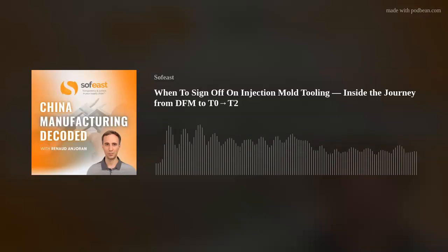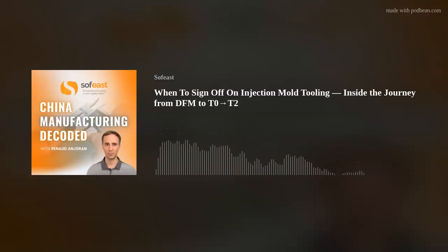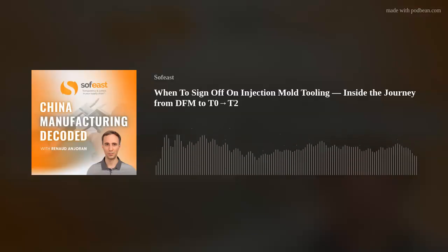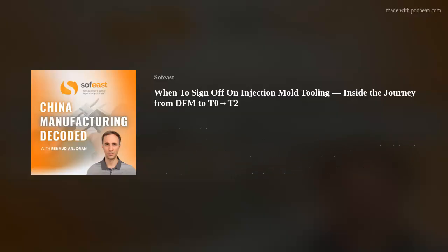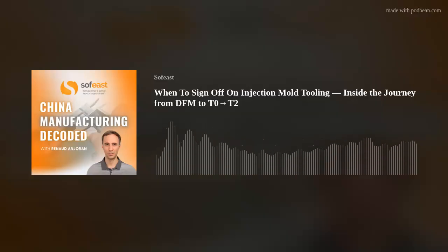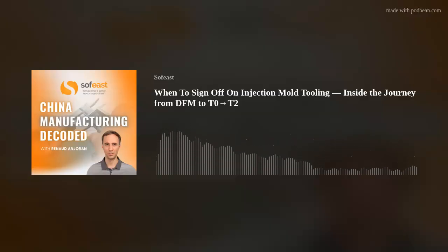Mark it up. Make sure that's very evident, because that would be, believe it or not, your golden sample. Now, it's more like a limit golden sample, because if it's got too many marks, well, this is the limit. So this is a reject. Anything better than that is okay. This is the time where we need to spend quite a bit of time going through this process, identifying all of these minor little defects that would be our limit samples and our golden sample from every single component that comes out of your injection mold tool.